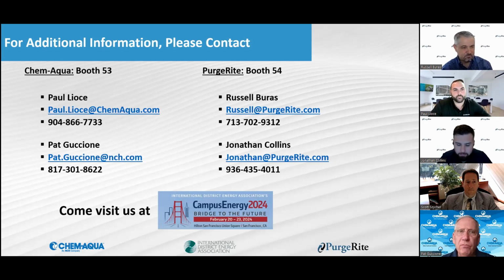You may need to add some specialty surfactants or dispersants, again, depending on the amount and type of biological activity you have in the system. Can be done, not particularly easy, can sometimes be painful from an operational standpoint, but very necessary. But once you get it clean, if you do a good job, it then becomes relatively easy to keep it clean over the long term.